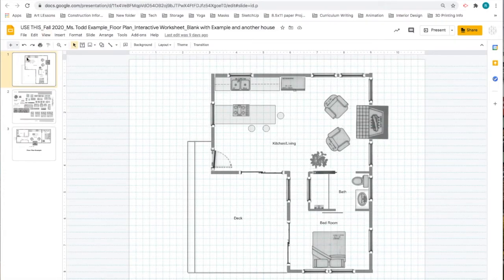And you might remember in my floor plan here, I actually have two sections that come together. The bigger section here is 23 feet by 14 feet, so 23 across and 14 here. If I multiply those two numbers, I get 322. This lower part here is 12 across by 15, and that adds up to 180 square feet. So when you add the 322 square feet plus the 180 square feet, it equals 502 feet.